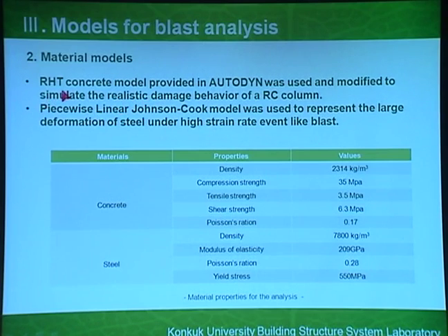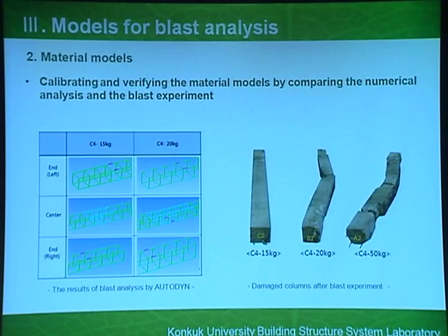We use the RHT concrete model and the piecewise linear Johnson-Cook model for steel. They require a lot of parameters, so we calibrated each value to match the experimental result. We carried out some test analyses to compare with actual experiments.